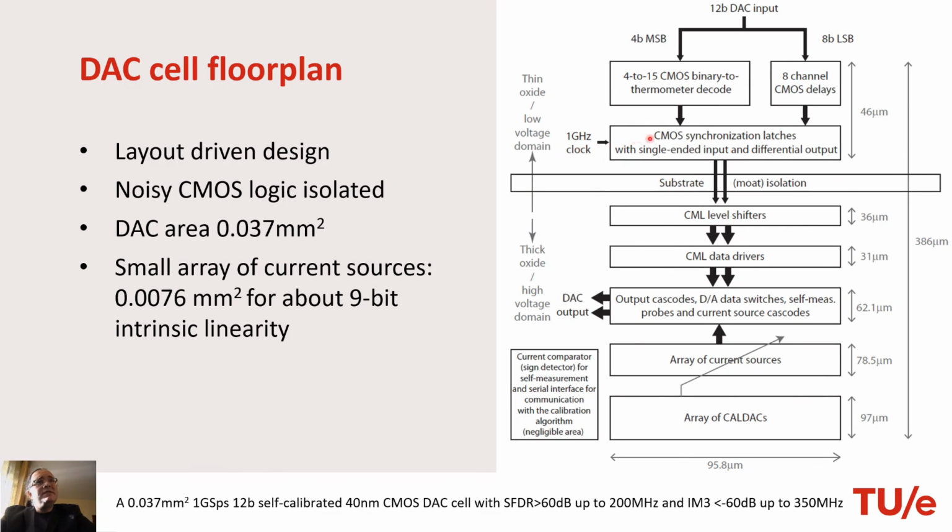The timing synchronization is done in the digital domain, thin oxide transistors, low voltage, so that it is very accurate. We have smaller, lower parasitics in thin oxide transistors, and we can have very accurate timing. Now, I already said noisy CMOS logic is isolated.